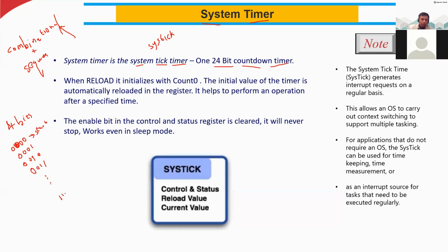And it will count up to 1, 1, 1, 1, where all the bits are 1. All the bits are 0 at the start, and at the end all the bits are 1. If you look at the numerical value, this is the binary value, right? In decimal, this is 0 and this is 15. So this counter will count 15 seconds. Let us say these are just 15 clock cycles, 15 seconds. So 0, 1, 2, 3 and so on up to 15.